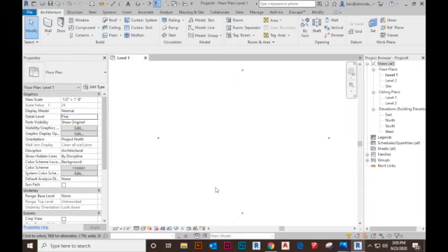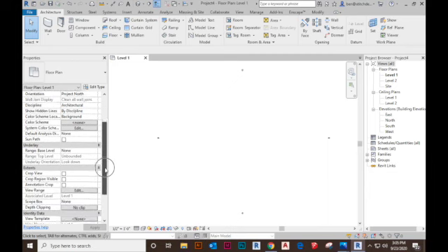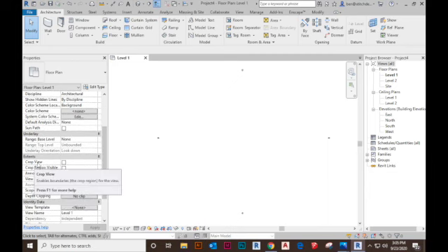As you can see, when we do change that scale, it makes our elevation tags relatively small. We want to keep those elevation tags in our view, but we don't want to see them for this tutorial. So we're going to scroll over to our Properties browser and enable our Crop View function under the Extents header. You can see that does nothing because our crop region is outside the borders of these tags. So to change that, we're going to also select Crop Region Visible under the Extents header.